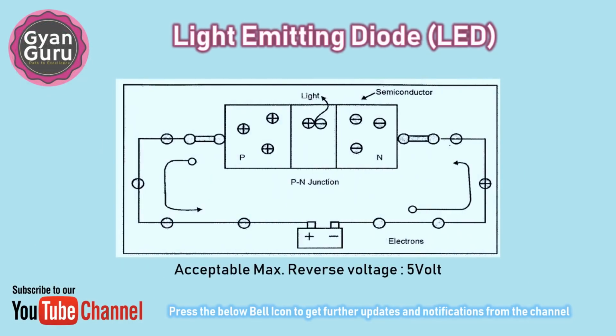LEDs are semiconductor diodes, which are electronic devices that permit current to flow in only one direction. The diode is formed by bringing two slightly different materials together to form a p-n junction. In a p-n junction, the p-type contains excess positive charges, holes, indicating the absence of electrons, while the n-type contains the excess negative charge, electrons. When a forward voltage is applied to the semiconducting element forming the p-n junction, electrons move from the n area toward the p area and holes move toward the n area. Near the junction, the electrons and holes combine. As this occurs, energy is released in the form of light that is emitted by the LED.